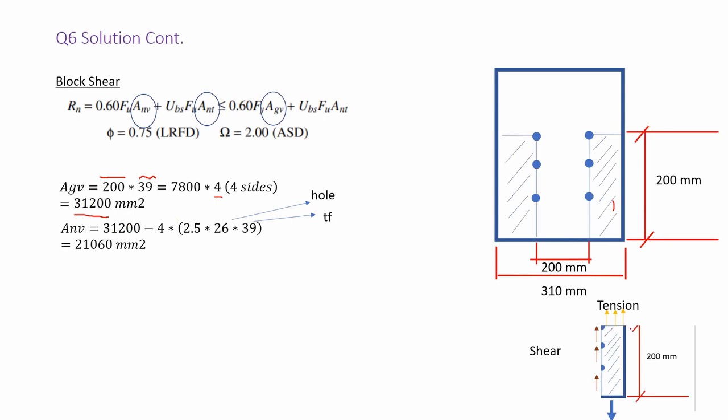We considered initially 200, but now we have to reduce it due to the fact that we have bolts in here. So from this side, we can see that the failure would take place in 1 bolt, 2 bolts, and a half bolt. So here we have 1, 2, and half bolts. Now, that 4 is appearing again. Why? Because, as I said before, we have 4 parts that are failing, this one, that one, and from the bottom. So I'm multiplying by 4.